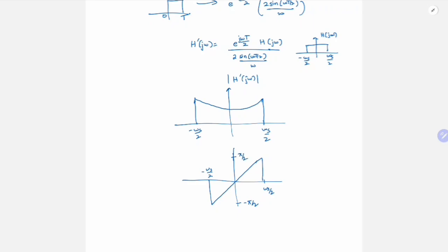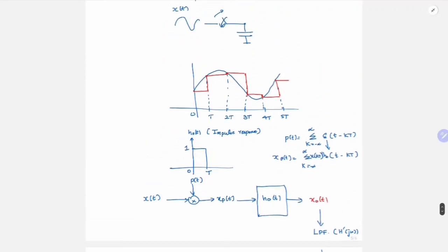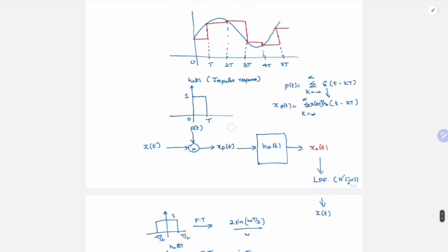So again, what this is trying to say is, if you use a different kind of sampling technique, let's say you needn't be this, it can be a linear sampling, right? From here to here you can join, here to here you can join, something like that. Then whatever the low pass filter you are using to get back your original signal will differ accordingly. So that is what this is trying to say.